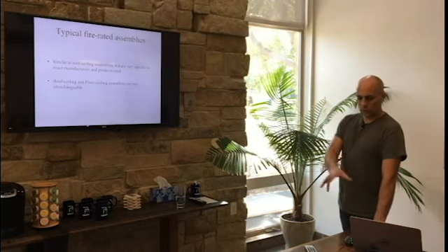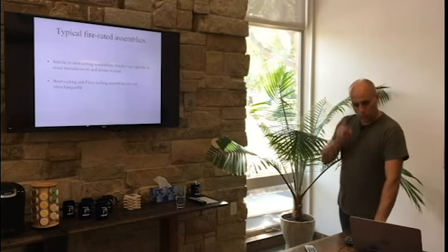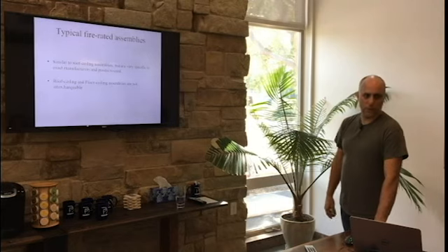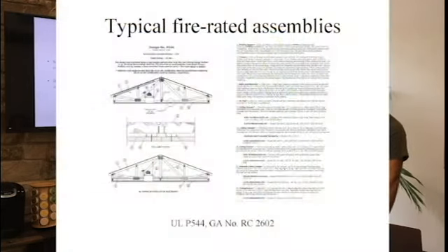But you see people all the time saying, well, it's 1 hour, we're good to go. No, it's only 1-hour floors, not attics. So it's really important that you do not mix up the assemblies nor anything that goes in between roof or floor. And we've seen our assembly, what the assembly is.